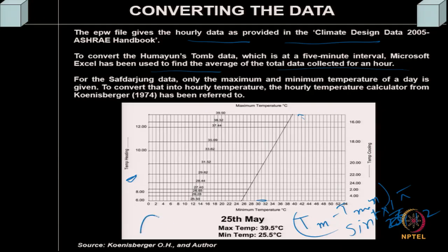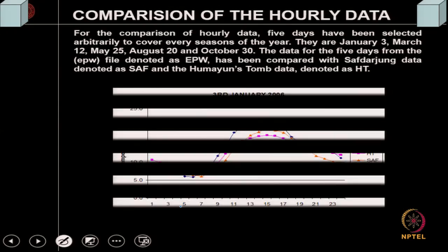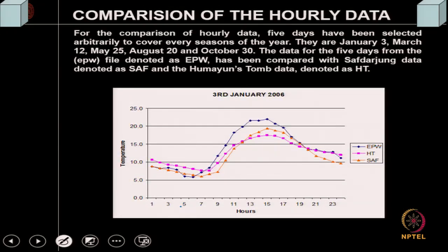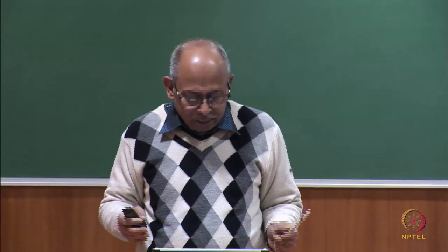So, one can consider sinusoidal variation of temperature, and this can be obtained because the meteorological data available were only maximum and minimum. So, one could calculate the heat load and cooling load for a building located close to that environment, and the cooling load that can be there if the building was close to that many number of trees.